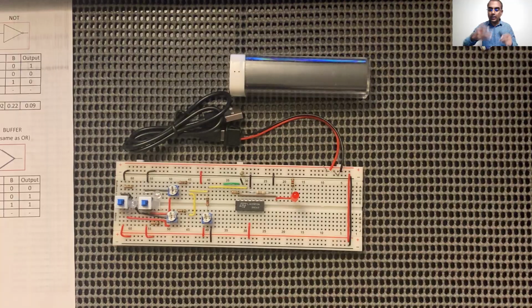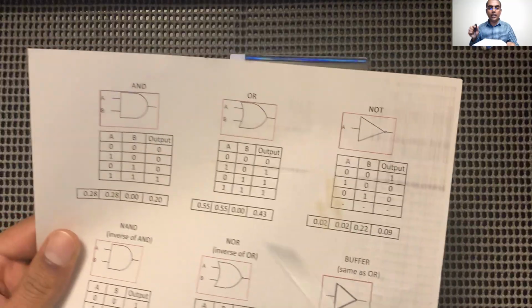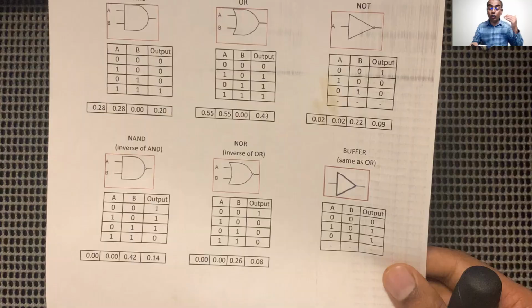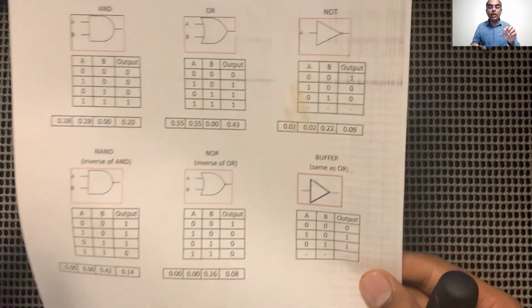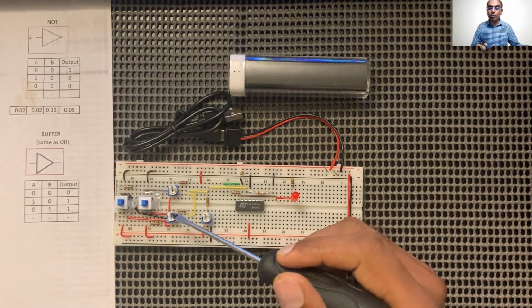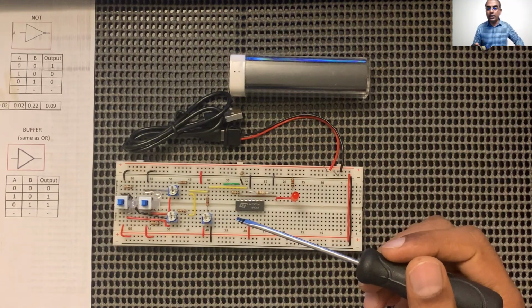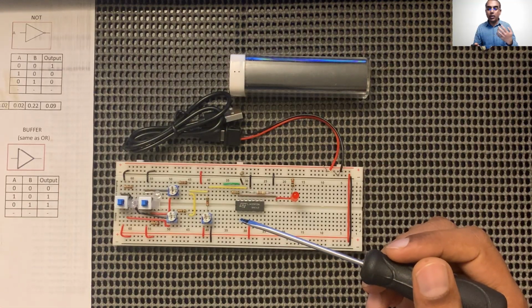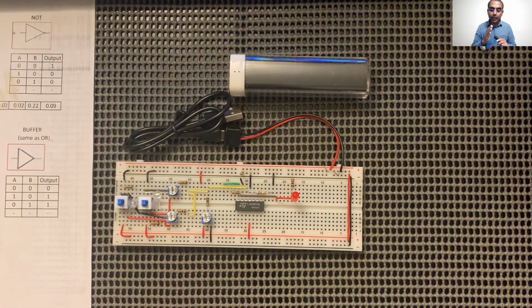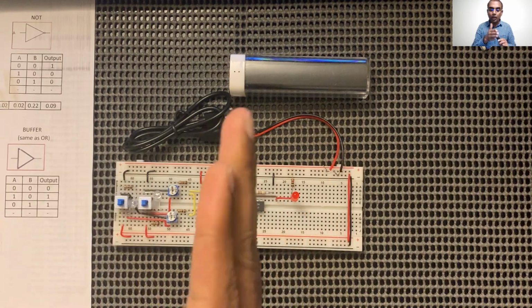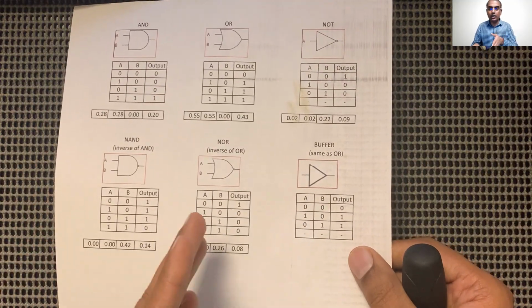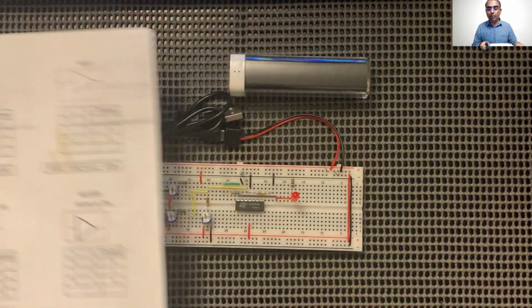Now let's start the simulation, and I'm going to start with the AND gate, the first gate. And I need to mention that it took me a few minutes or a few hours and a lot of back and forth to achieve the correct potentiometer values. You see, the potentiometer is the one that acts as the weights in our case. So it is on a trial and error basis that we have to find the correct potentiometer setting or position to achieve this AND gate or pretty much any of these gates. And that is how we train the perceptron.